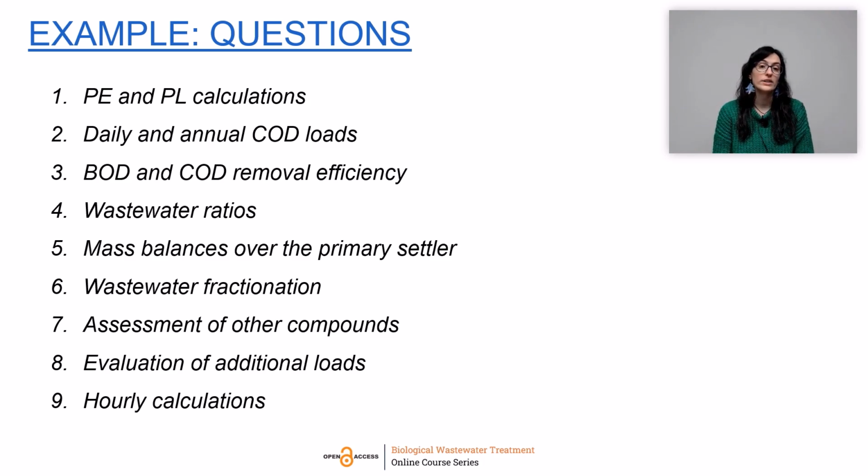We will evaluate wastewater ratios. We will also set up the mass balances over the primary clarifier and also perform the wastewater fractionation. We will assess as well other compounds present in the wastewater, and we will evaluate additional loads as well as perform some hourly calculations.